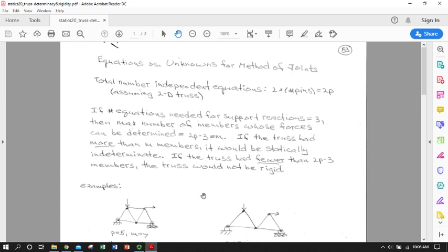Sometimes that's possible. Sometimes we might find that nonetheless we can't put the whole truss into static equilibrium, which might mean some of it can move relative to the other, and that's called instability, just another form of not being in static equilibrium, or lack of rigidity, because you can have one set of members accelerating, moving relative to the other. And so it's good to know that ahead of time and not get halfway into a complicated, cumbersome set of solutions only to find that, oh, we shouldn't have started.